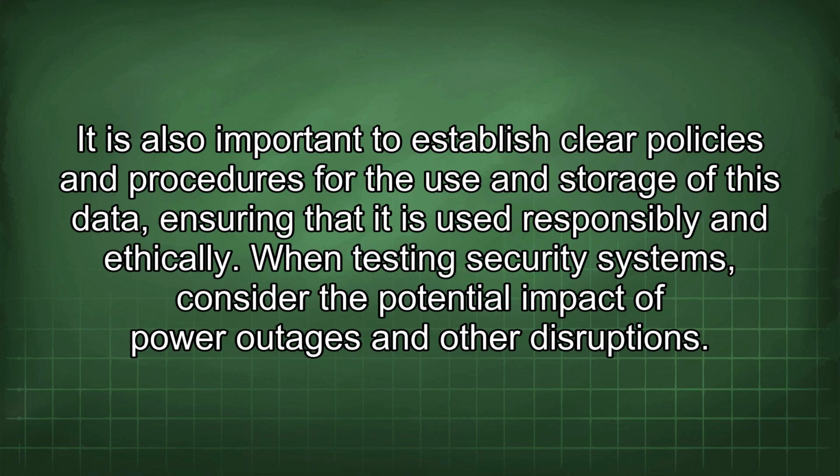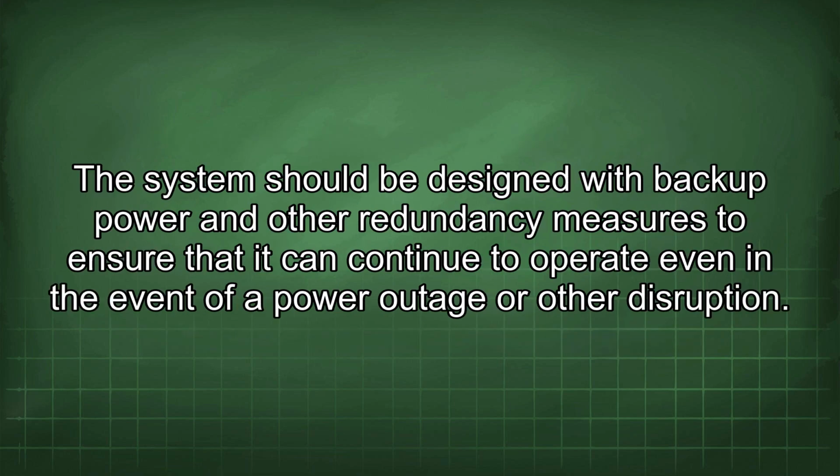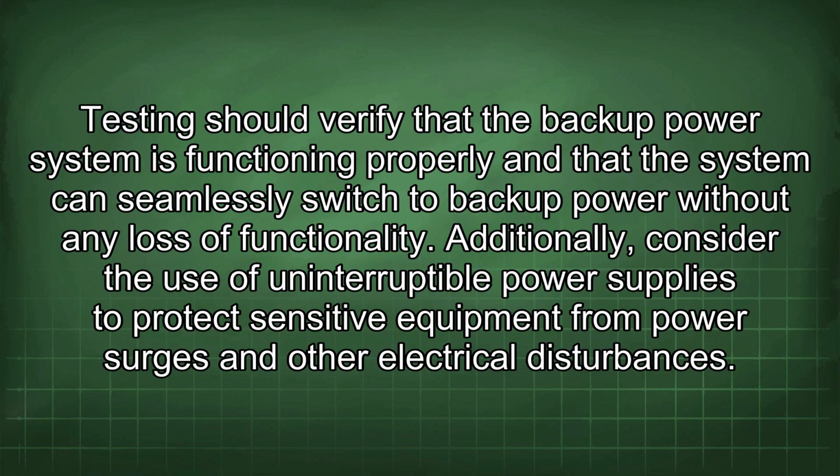When testing security systems, consider the potential impact of power outages and other disruptions. The system should be designed with backup power and other redundancy measures to ensure that it can continue to operate even in the event of a power outage or other disruption. Testing should verify that the backup power system is functioning properly and that the system can seamlessly switch to backup power without any loss of functionality. Additionally, consider the use of uninterruptible power supplies to protect sensitive equipment from power surges and other electrical disturbances.